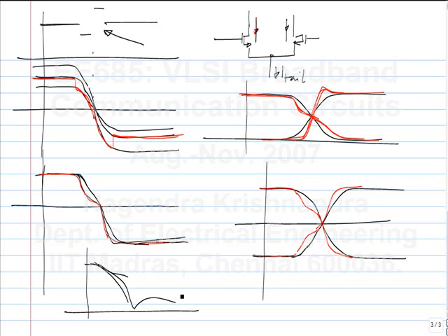And actually, that itself is not the problem. Here, the ISI can become nonlinear. The interference to one symbol from the previous symbol can somehow be non-linearly related, in which case it cannot be removed by a linear equalizer. That is the main problem. If you can relate the intersymbol interference as a transfer function of a filter, then you can undo it with another filter. Whereas if it is something non-linearly related, you can't remove that.